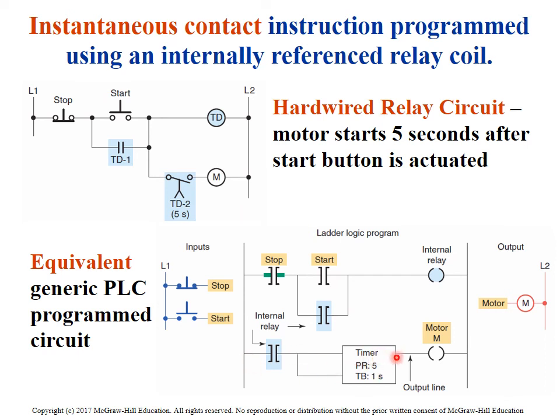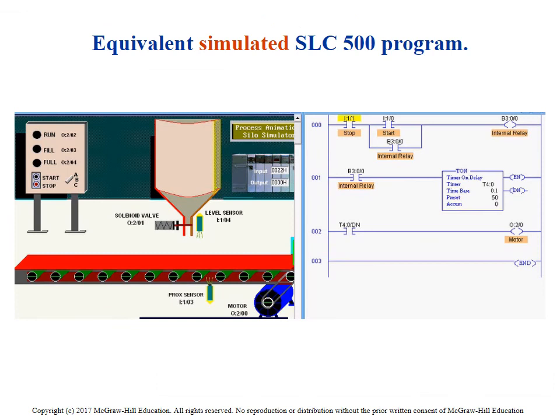And here's the same thing done only with a PLC program. As you can see, the wiring for a PLC is way easier. It's just point-to-point wiring, whereas here you've got to wire from this point to this point, this point to this point, and so on. You can see a lot of terminal points here, a lot of room to make errors.